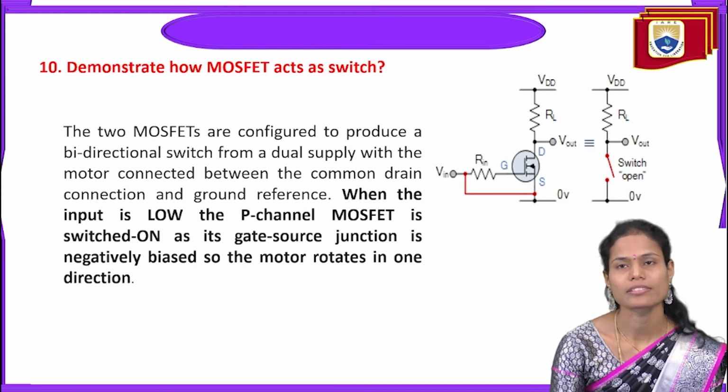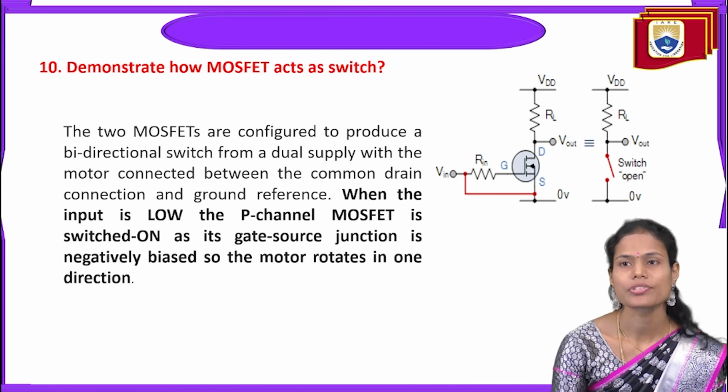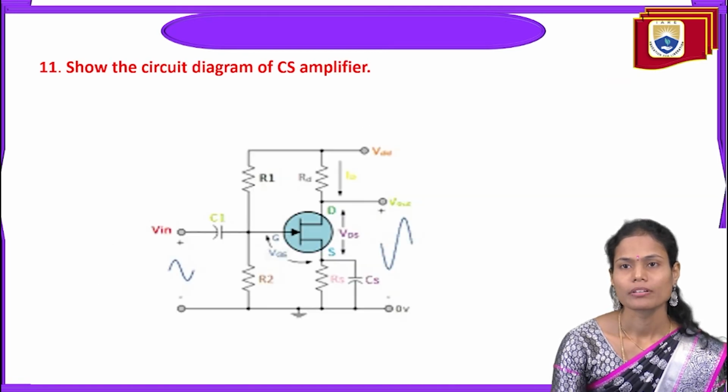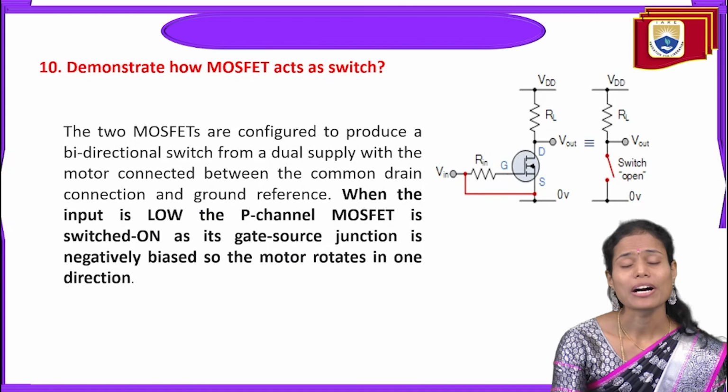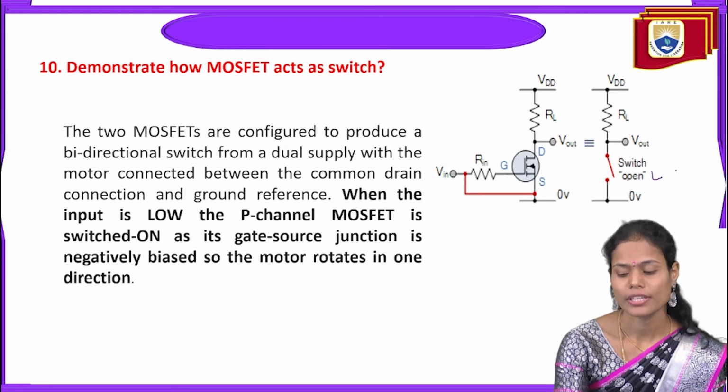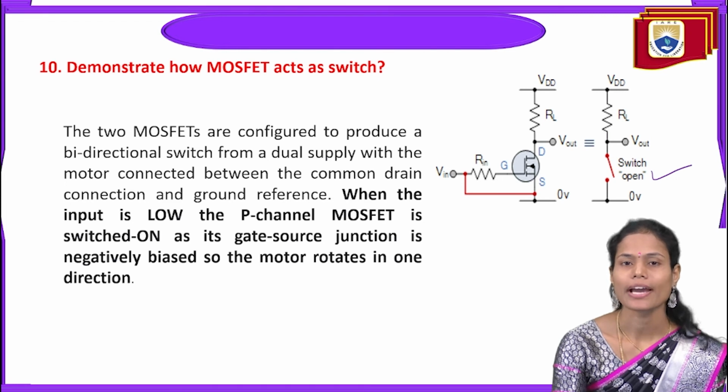Demonstrate how MOSFET acts as a switch. I have already mentioned once the MOSFET is operating in the cutoff region, it acts like an open switch. Once the MOSFET is operating in the saturation region, it acts like a closed switch here.